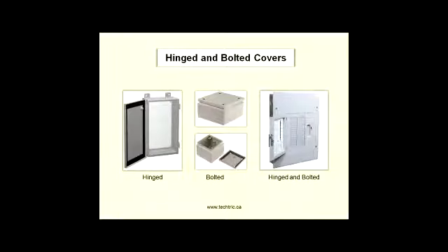And what do they look like here? Hinged or bolted covers. Well, there's a hinge, just like a door, and you open it, so that's a hinged cover. And this is a bolted cover, right? There are bolts. And this one is both: there's a hinge, and there are also bolts to hold that cover. How can that cause an arc flash? Well, there could be some elements resting against those covers, and once you make some physical movement in there, things can happen. So always take precautions when you're doing this kind of job.